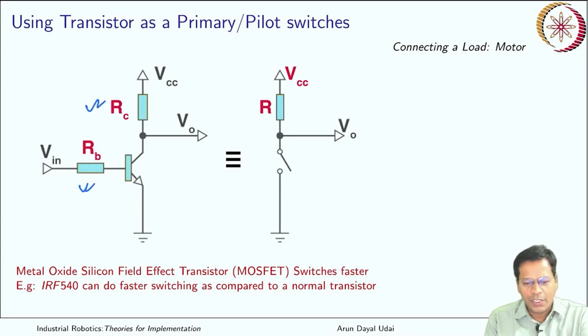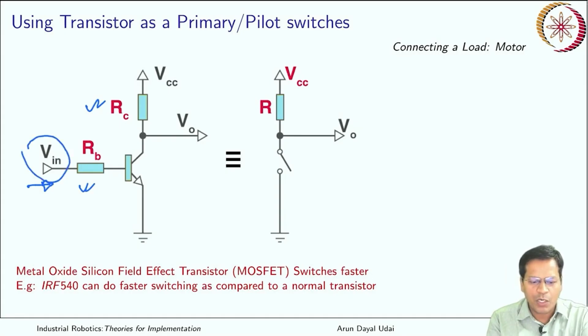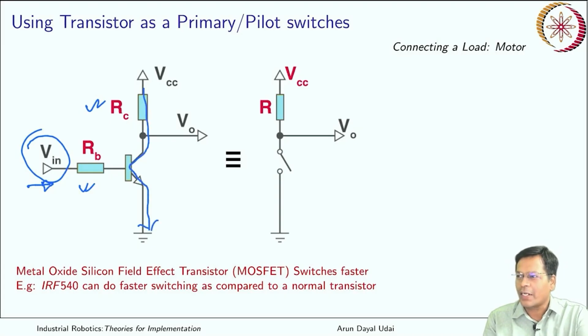If it is in a switching mode, not in the amplification zone, it has already saturated. In that case, it is just about to saturate with even a small amount of current fed from here. So if you apply a small amount of current from here, it will get biased and current goes from here to this, okay, and current flows.